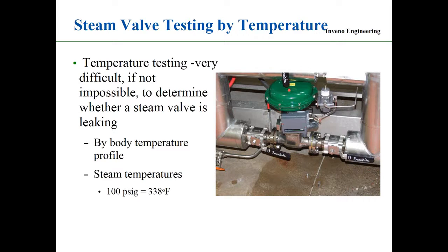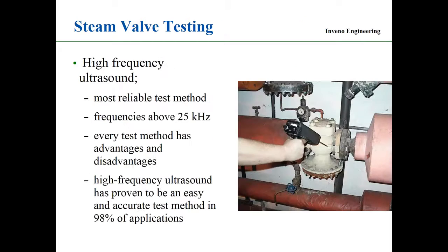Energy is going to be transferred from the valve body to downstream, and the valve body downstream is going to be hot, just through conduction. So testing the valve by temperature is quite difficult to do. We have to come up with another way of testing.